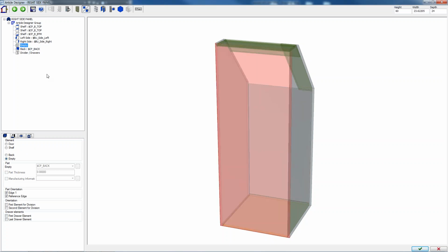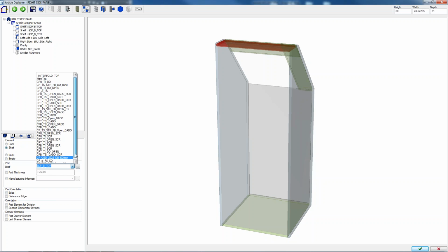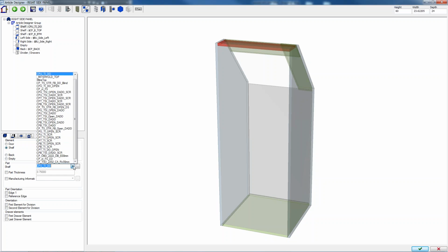Okay. So you just need to put a full top on both of the tops rather than rails. Yeah, that has to be. Your default is using your variable, your default's rails. So you'll want to go pick a top that's a full top, or make one or whatever. That third one down. Count down from the top: 1, 2, 3. There you go. Same for the other tops.